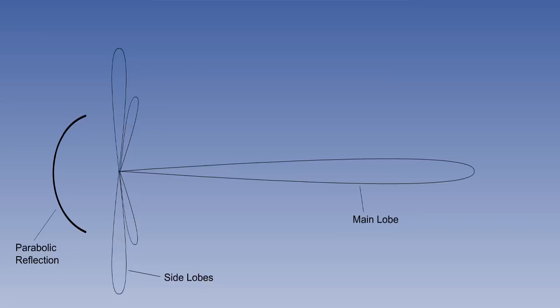Because the focal point is minute, the energy from the waveguide will cover a slightly larger area, and there will be some spillage of energy which causes side lobes to be transmitted. These may cause radar returns from outside the target area of the main beam.